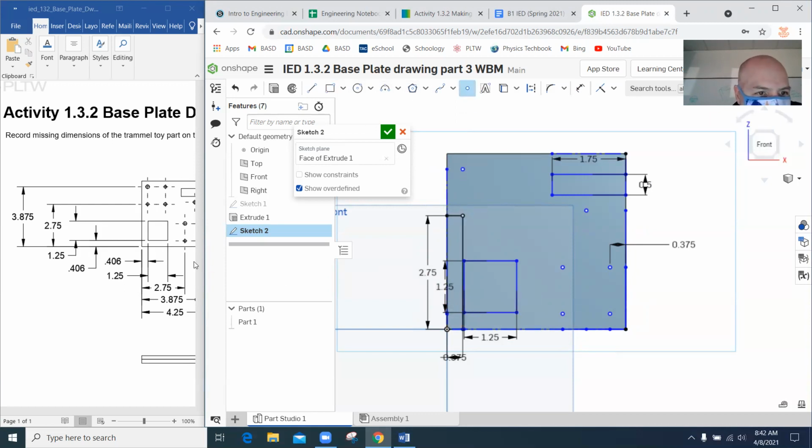I might go back and delete it later, but for right now, what am I going to do? Remember, I'm going to try to go for a sort of symmetrical or matching situation here. So I want that, looks like 1.125, enter. And then it looks like that is 1.125, enter. Now these I'm just using to check. So I'm doing a construction rectangle here.